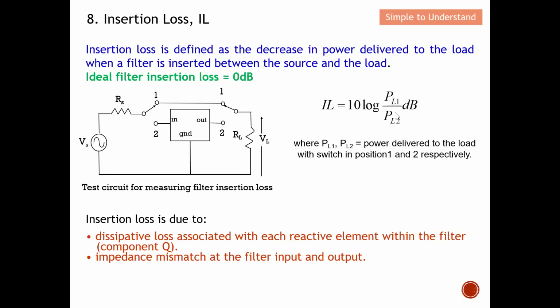From here, you can see that the definition of insertion loss is shown over here, which is 10 log of the power that you obtain without the filter, over the power that you obtain when you insert a filter between the load and the source. So this is the definition of insertion loss.